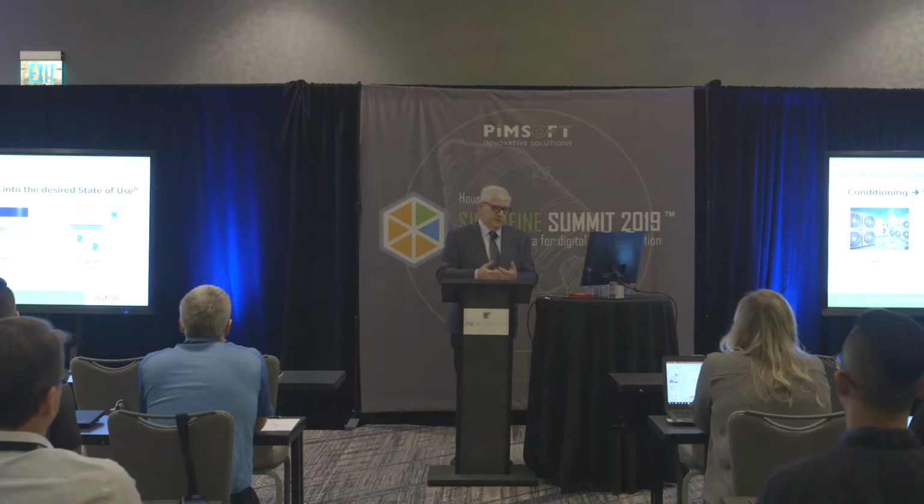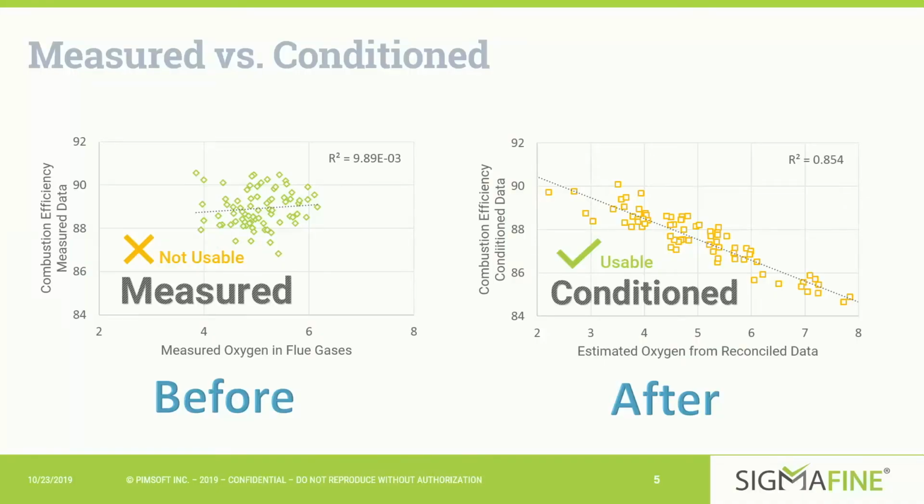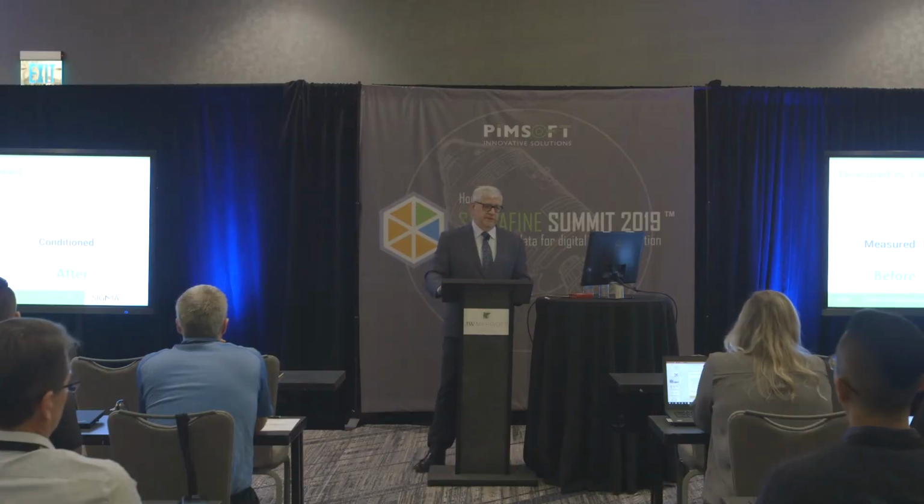So data reconciliation and data validation are just methods. So far, we've used the methods to do mass balance. But the situations have evolved, and last year we introduced conditioning data. Probably the most famous slide that every one of you has seen is the before and after slide. If you don't condition your data, you get what's happening on the left-hand side: no correlation. If you condition your data, the same data, with no data cleansing, nothing, just applying basic Sigmafine, you get something that's usable. That's the whole story of using Sigmafine for data conditioning in one slide.